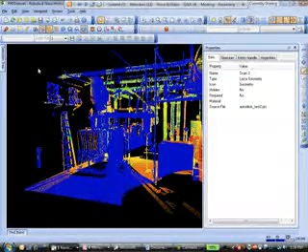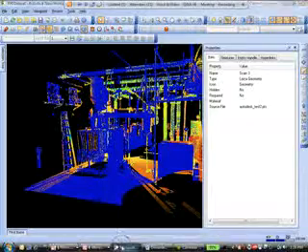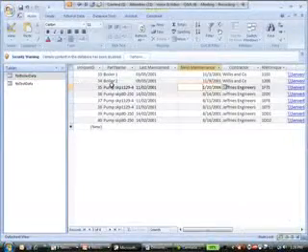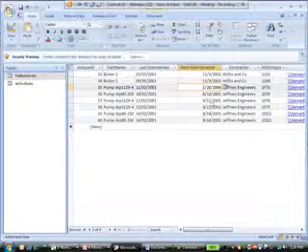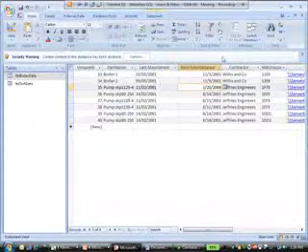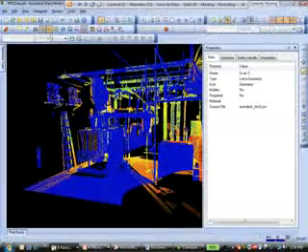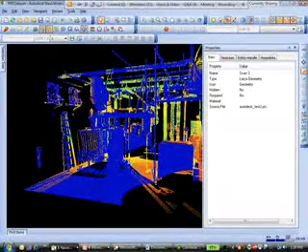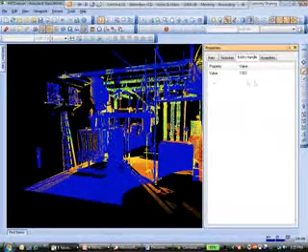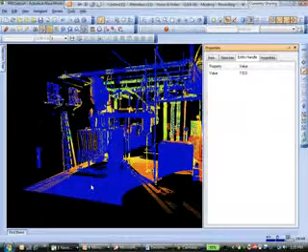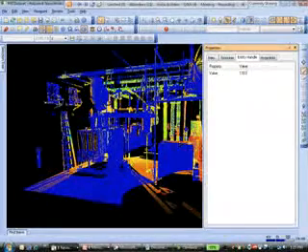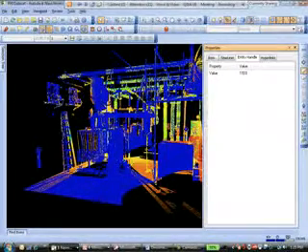We can take this information that's in here, and now if we have an outside database, so for example, I have an Access database that has some general information about boilers and some of the pumps that would be incorporated in there. Inside of Navisworks, I can now create some specific handles, like what I've taken is some of the existing information, but I can create my own values in here. So I could put in a marker or a tag, which then can be referenced by that database.